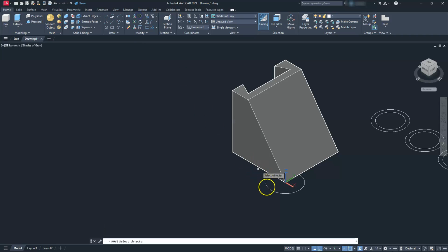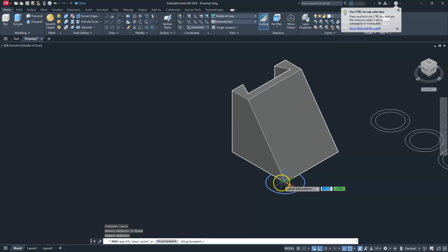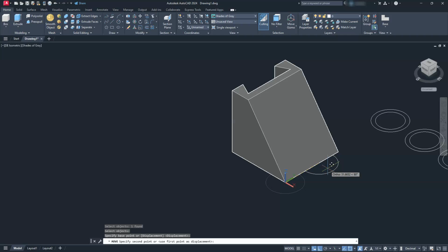So when I go to move this object, I'll select it, and I'll select the center because that's where I want to move this thing from. And then I can type in the actual coordinates, right? So starting with the X direction, that's going to be a negative 18.1. Go ahead and put a comma in, and then I have to tell it the Y direction. And then the Y direction in this case will be 25. So once I type in those two numbers and hit enter, it should automatically be there.